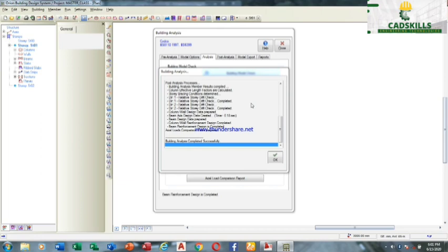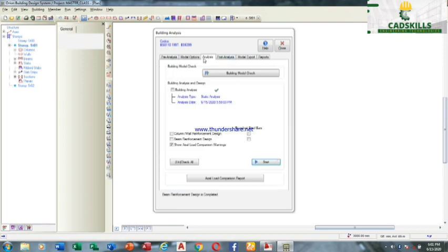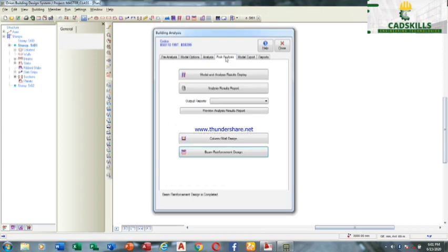You can see building analysis completed successfully. If it's not completed successfully, brother, you are not finished. You have to go look for what the problem is. I click OK here. After the analysis, I go to post analysis.